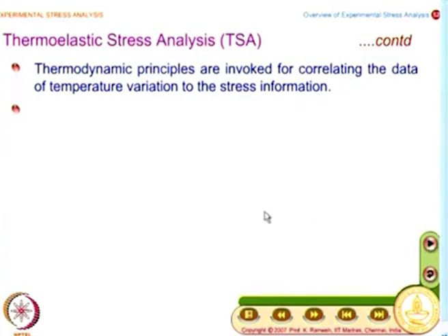So, as you go advanced, you also have more complicated mathematical development to interpret experimental data, and you have to be very careful in conducting the experimental method. You should be worried about other thermal sources, and you should suppress them, because you are essentially recording the emissivity of the surface, whatever the emissive characteristics, and if we have other sources of thermal disturbance, they have to be suppressed. So, the experiment has to be conducted very carefully,